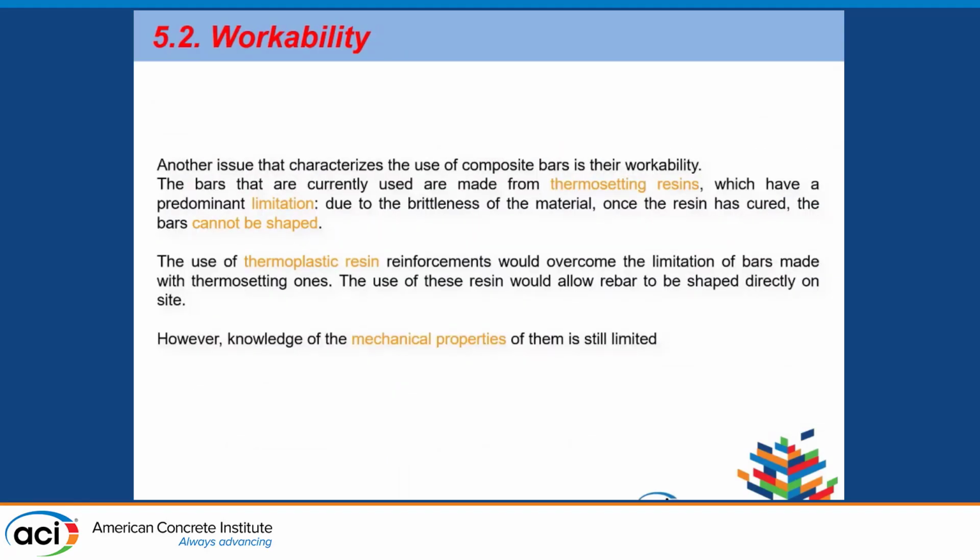Then another key aspect that must be studied in further detail is related to workability. That's because FRP rebar are mostly produced using thermosetting resin, which, once cured, is brittle, so the bars basically cannot be shaped on site. This can be a limitation in several cases.